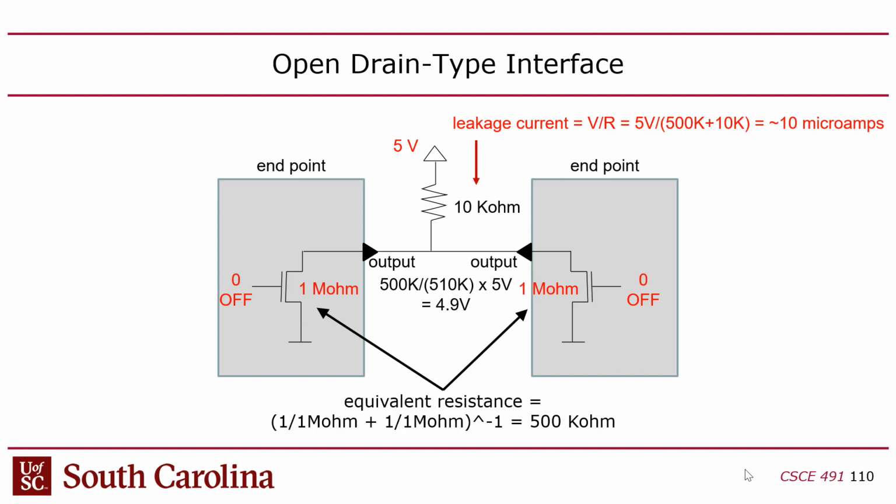Somehow there's a circuit in there that's going to detect if I try to take mastership at the same time someone else does. Unclear how that works, but there's a mechanism in there. And in the case of I2C, they use the open drain style where they just have a pull-up resistor, and if no one sends a bit, the wire is 1. Actually, it's slightly below 1 because there's going to be a voltage drop over that resistor, but a small one.